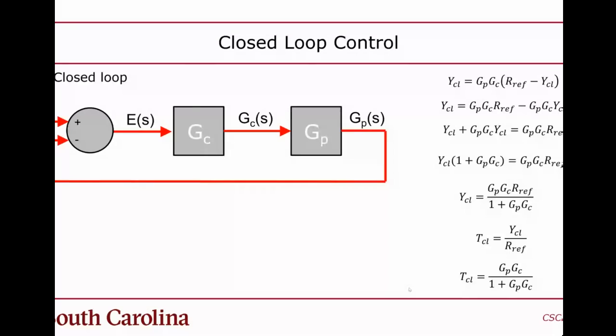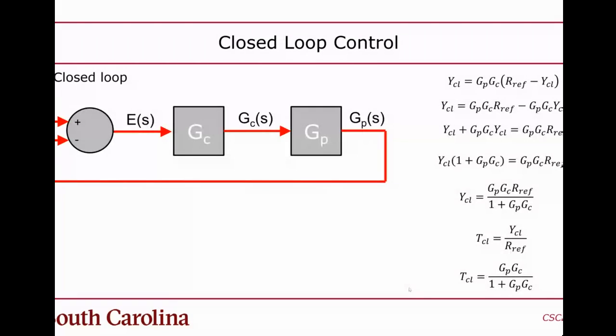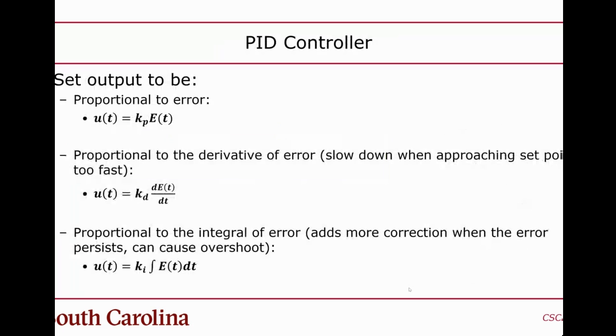And it doesn't have to be exact. Your open loop transfer function might look different because it may have more things, or it may even be nested. But like I said, this is basically just your classic closed loop control transfer function. Now, again, as you might imagine, in order to work this out you have to do some algebra. You have to do the multiplication and then work it out to get the S domain transfer function into a nice ratio of two polynomials.